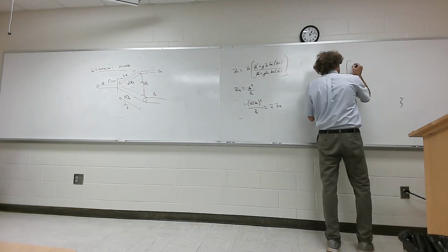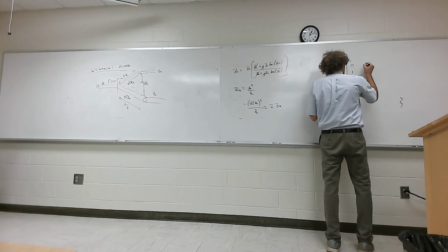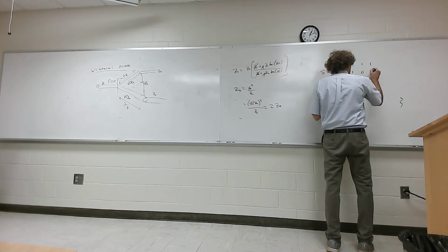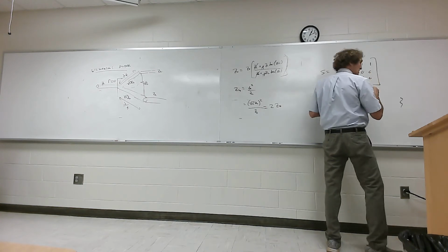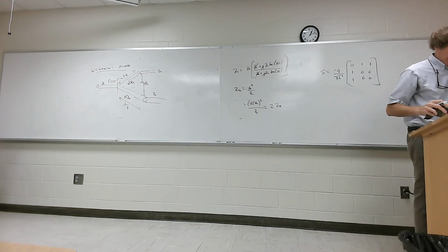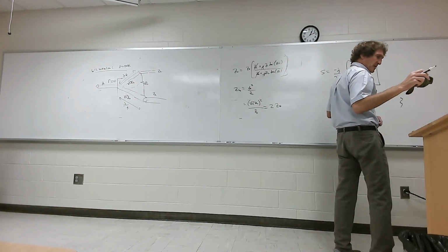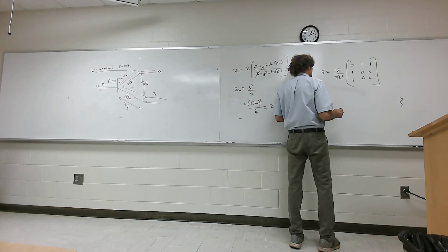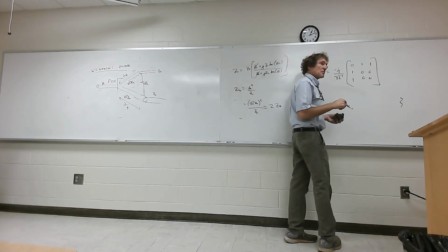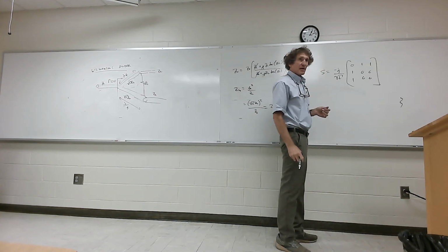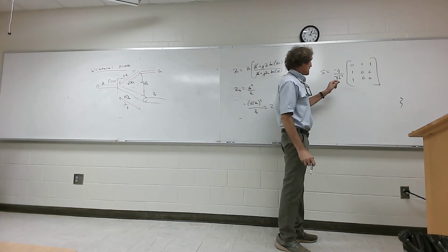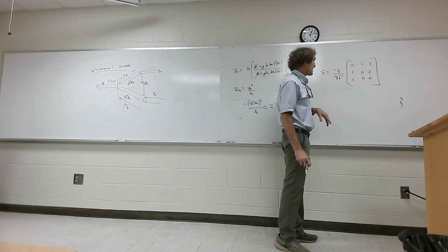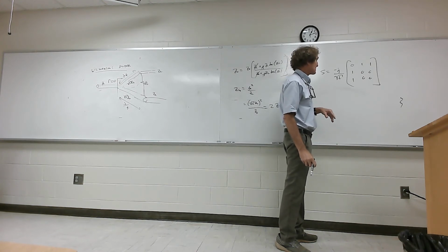It's just 0, 1, 1, and then 1, 1, 0, 0, 0, and 0 everywhere else. Oh, I'm sorry, not quite the same as the other one, but it's 0 everywhere else. This is the Wilkinson divider, and these are the S parameters for it. It's shown in his book. You'll notice one thing when you look: that minus j right there, that's a 90-degree shift, and that's something to observe here.